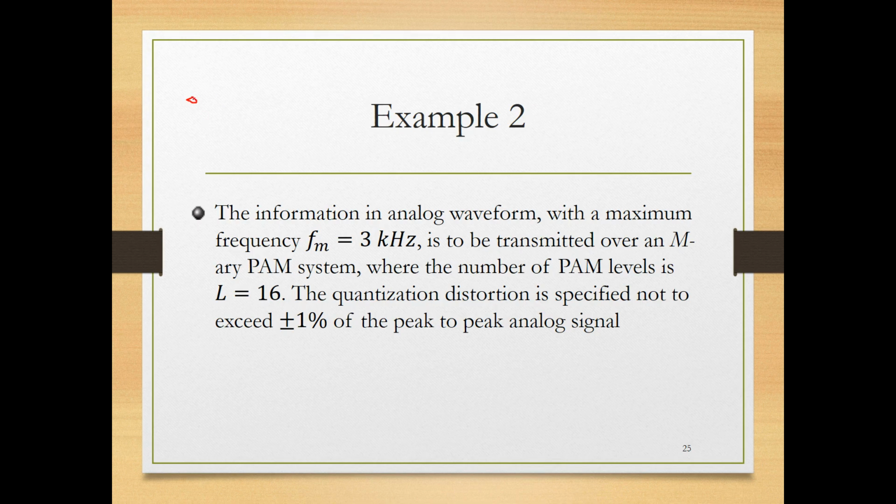We said if we have 0, 0, then we have this level of power. We have a pulse of this level. If we have 0, 1, we have a little bit higher amplitude. If we have 1, 0, a little bit higher. If we have 1, 1, it's even higher. We call it pulse amplitude modulation. We map different groups of bits to different amplitude levels. This is your modulation rule. What do we call this? This is 4-PAM, 4 pulse amplitude modulation.